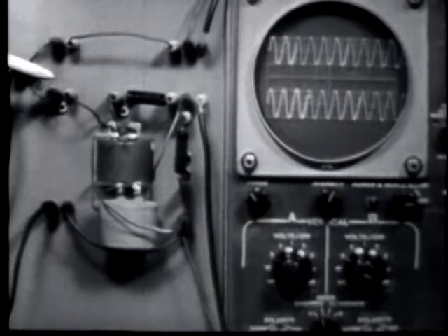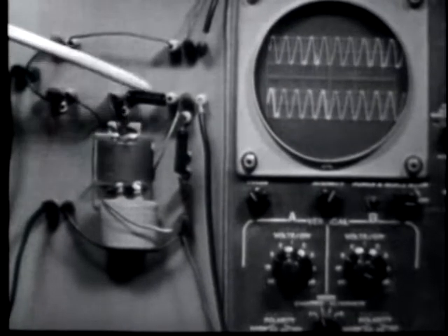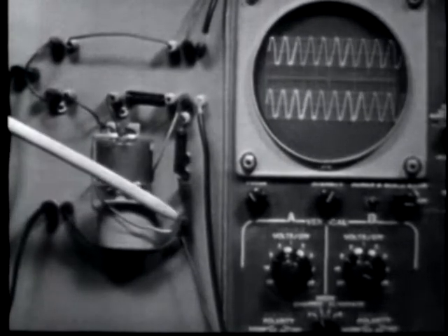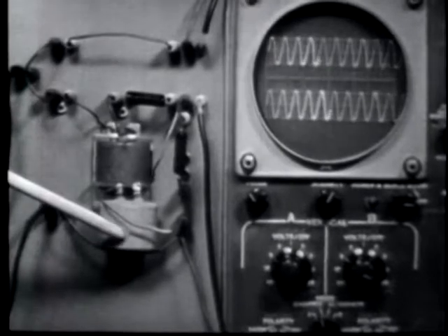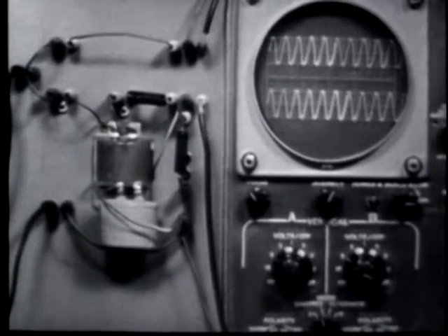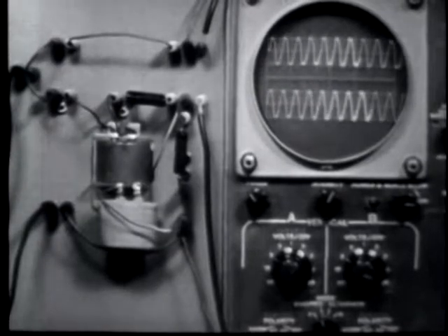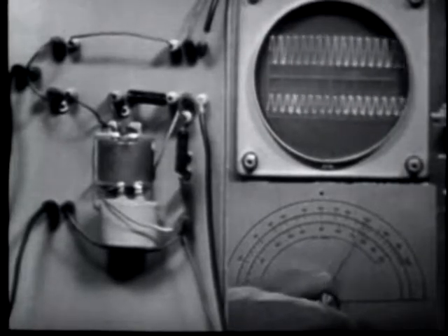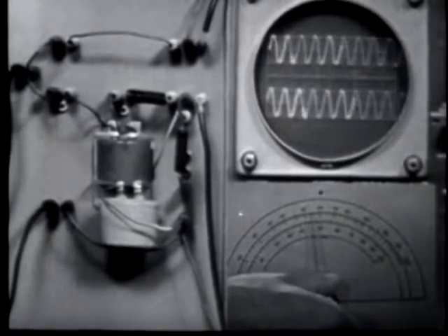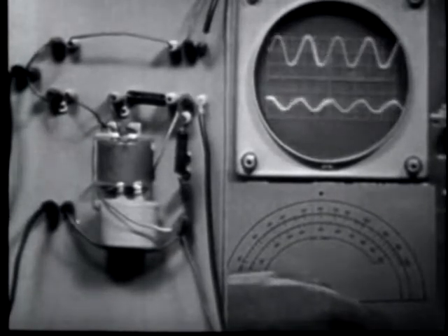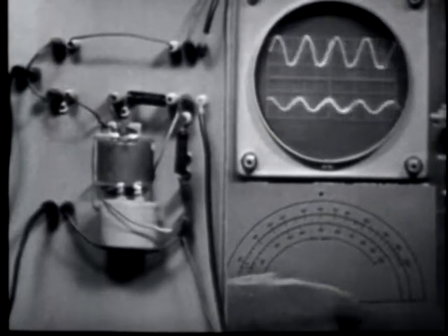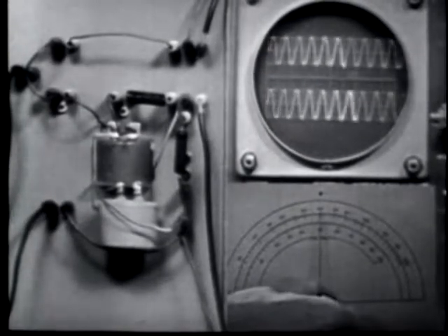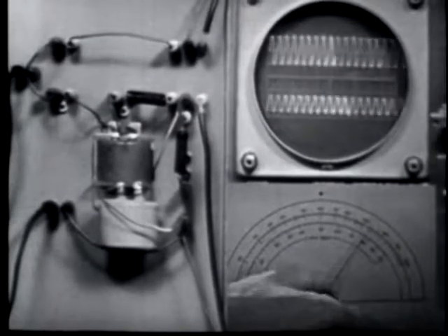Now here's the series tank in the series position. Inductor, capacitor in series. And the parallel tank in the shunt position. This is our parallel tank inductor, our parallel tank capacitor. Let's see how this combination affects our output signal. As you can see, the circuit is functioning as a band-pass filter. Now notice the good attenuation of those frequencies off resonance and the sharp response of the filter at resonance. Now this is due to having two tanks providing the filtering action.